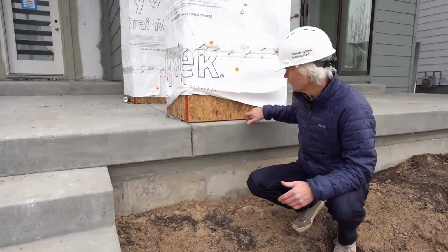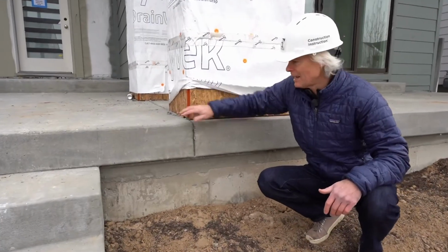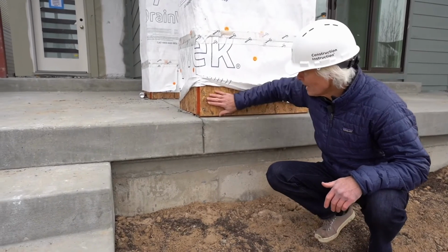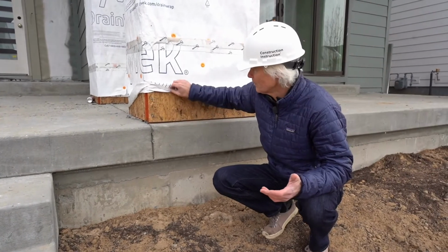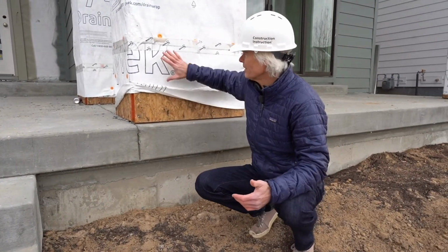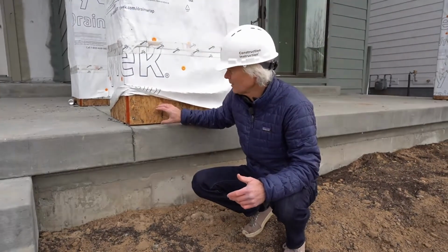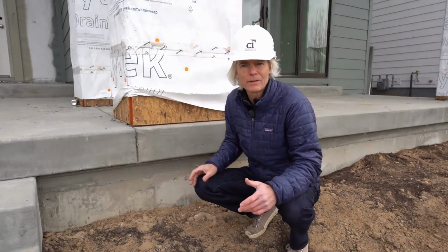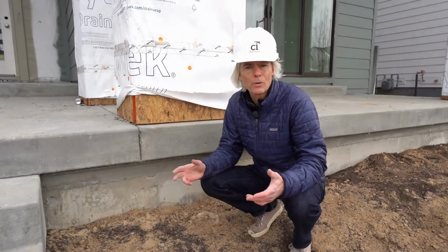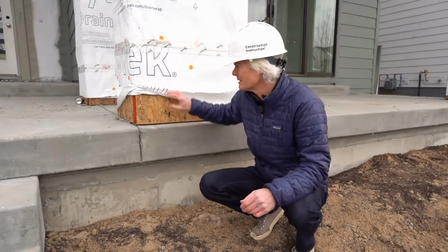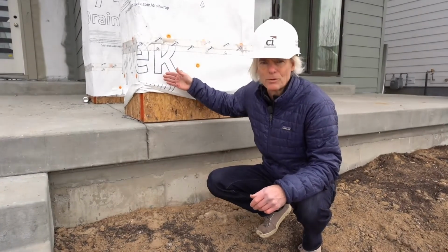But what we can see is we've got structure behind here, and we've got treated lumber directly in contact with this porch. And then you can even see the weathering that's happened before this is even covered up with this OSB material. But they're going to probably flash this, come down, again, grade D paper, and then the subsequent layers go over the top of it. So you look at that and go, wow, are we creating some way of draining and releasing water? We've got a pretty good start here, but what we really want is a clear 1/4 to 3/8 inch drainage space between this material here and the actual scratch coat.